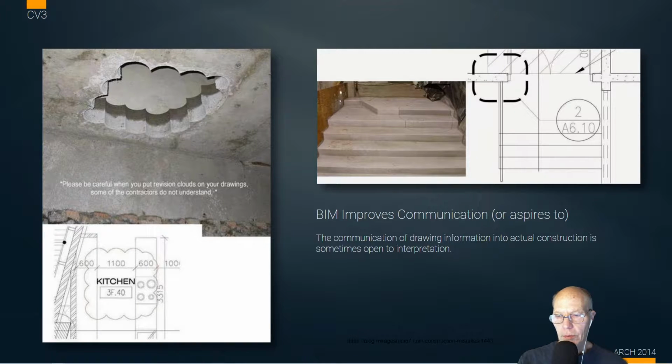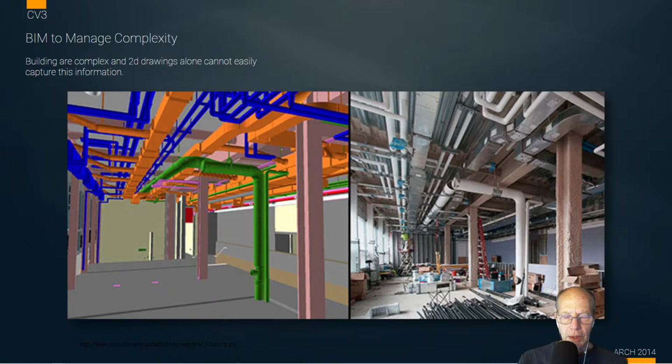The other thing is the stairway here. This is 3 steps going up to a landing, but the person who poured the concrete read the label or the takeoff for this detail as a line of a step and actually physically created that step. So these really just point out the problem with not having the usefulness of a physical model to create our understanding of our projects.